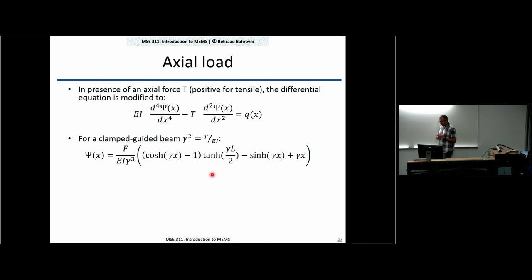Another issue, and you already have seen it, is that you can have a stress inside the film, or an actual load on the beam while it is bending. An actual load on the beam, as it is bending, is going to affect its bending behavior as well. The Euler beam theory has to be modified as shown here. You now have this tensile force that is applied.